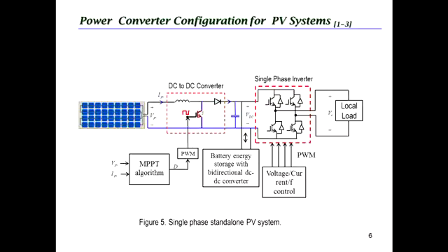Okay? So this switch is operated with an MPPT algorithm so that whatever maximum power is available can go to this capacitor. All right? And depending on the capacitor voltage, we then decide on the current that goes into the local load, if it can absorb it. If it cannot absorb it, if we are producing more power than what the load can absorb, then it has to go to a battery.